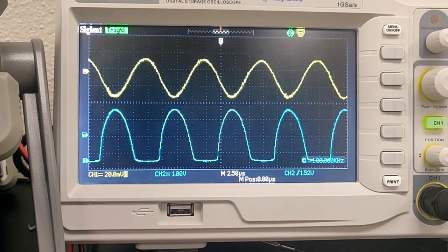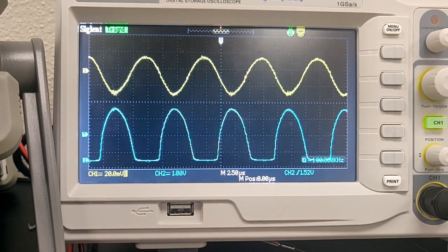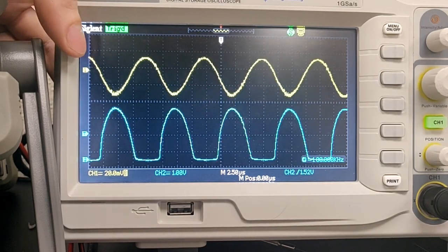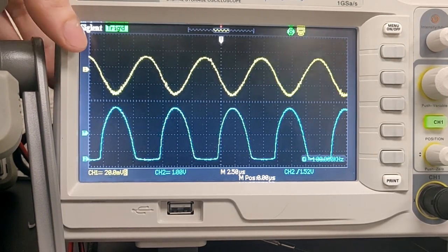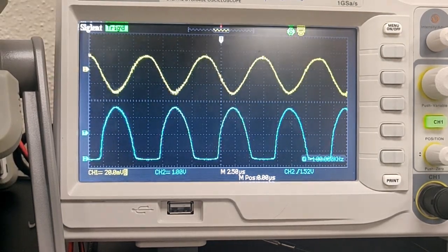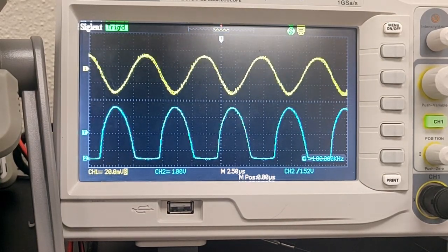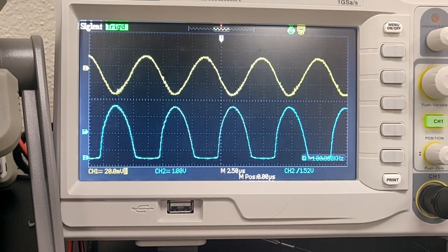All right, so I went ahead and built the circuit from figure 8, and what I have shown right here on the oscilloscope is that channel 1, the yellow, is that V1 output from the figure, and it's just the raw output from our signal generator. Right now I have it set to 50 millivolts peak to peak.